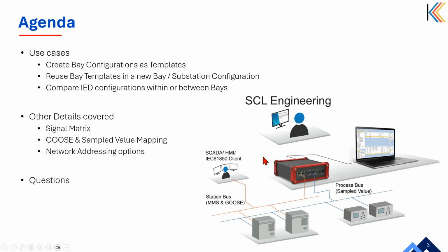And recently we added the BNet hardware into our offering. BNet is a hardware accessory that works with test set, and it allows you to monitor sample value traffic and even simulate the sample value traffic. In the recent version of IEC 61850 test set, we have added the fault simulation capability and PTP master capability. So you can test your relay for basic functions without any other hardware. I'll not talk a lot about the other tools. We'll focus on the SCL tool in this webinar.